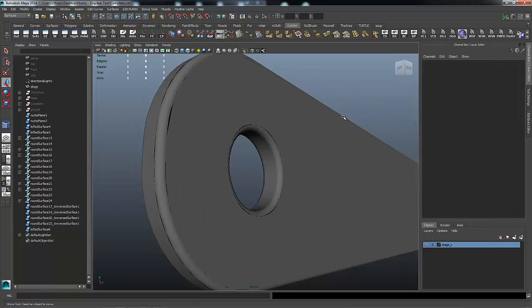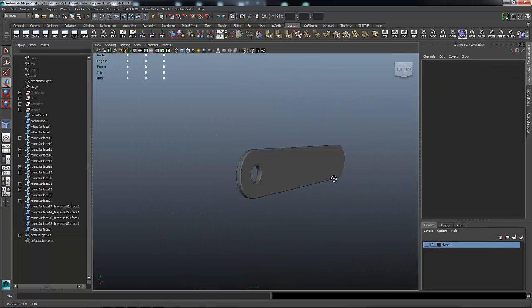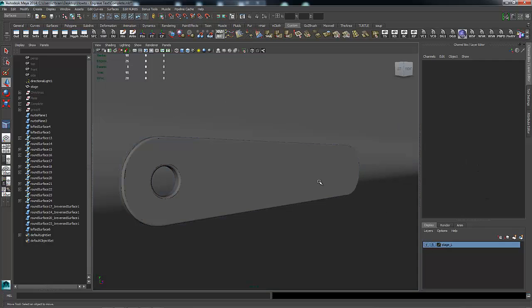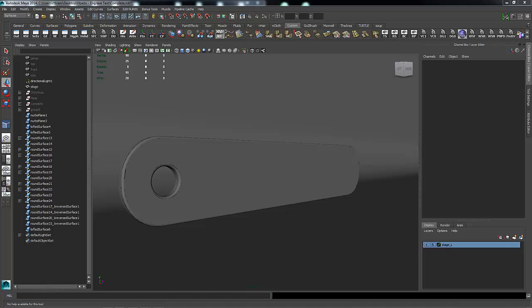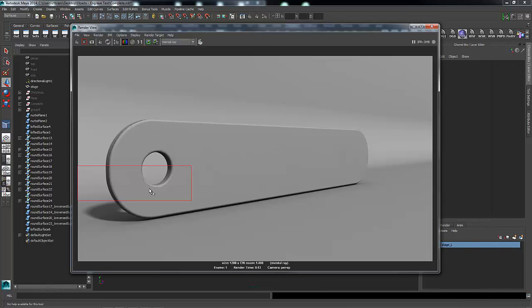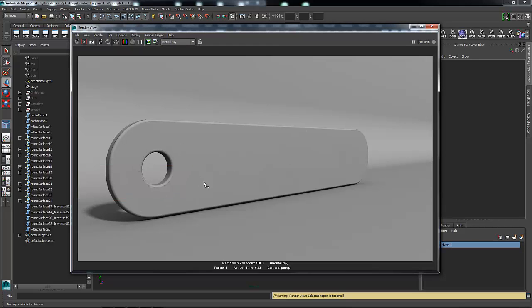So now we don't have any weirdness in there anymore, and we've created this surface with nice rounds. Once again, don't worry about the gaps. When you come in here and you render it, you won't see those. I'm going to show you. I'll turn the stage back on here, and if I do a very fast render, okay, render's done. So you can see when it renders, you don't get the gaps.